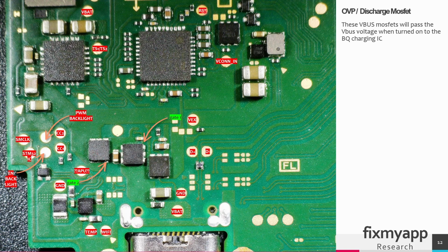This test point is a reset line that goes into the power delivery IC. This comes from the APU. So this is the VCon in. This is the 5V power rail generated by, I think, one of these voltage regulators. Here you have TS1 and TS2. Here's a voltage divider, and this voltage divider is used to set a specific configuration in which this charging IC operates. You set some kind of temperature window.